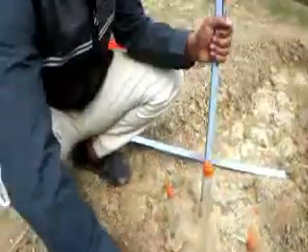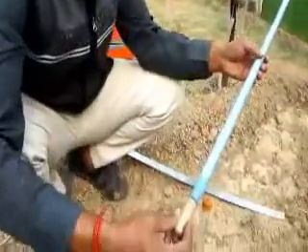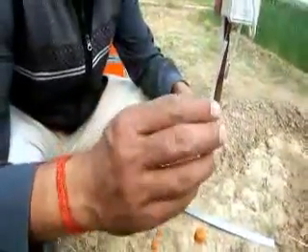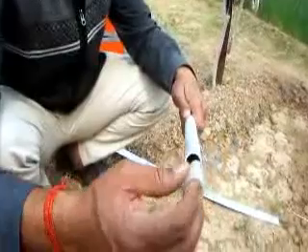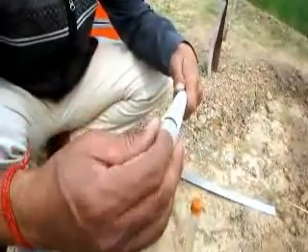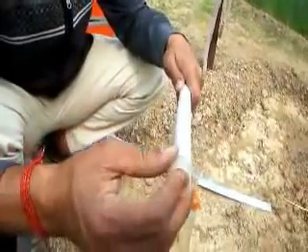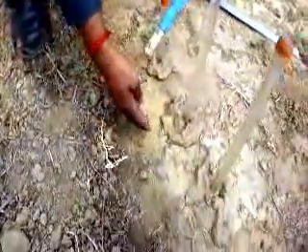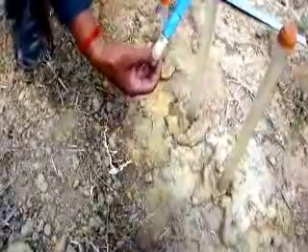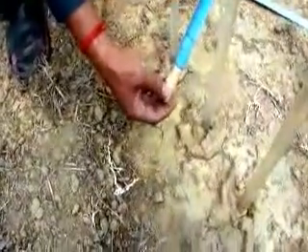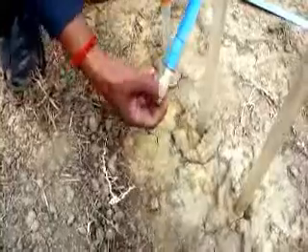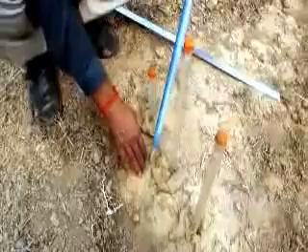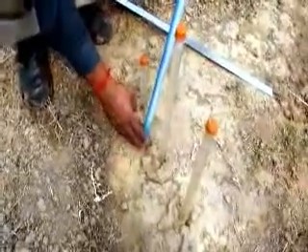What is a tensiometer? You have already learned in your theory. It has a porous cup and a tube. The tube is filled with water, and once it is filled, we put a cap to seal it from the top. Because of the dry condition, the soil exerts a suction pressure on this cup, which allows water to balance between the moisture content of the soil and the water inside.